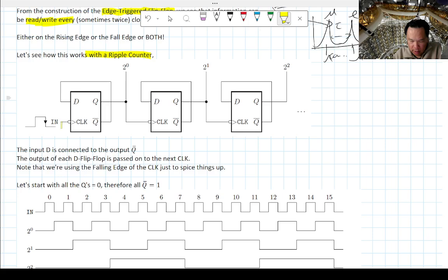The construction is that you have a D-type flip-flop that takes an input of a clock, and it can also take data in. Remember, this data actually goes into two gates, one for R and one for S, but the S is inverted compared to the R. It has two outputs, Q and Q bar, and they're always going to be opposite of each other. The weird thing is that the Q bar output gets mapped to the input. So there's no external input except for the clock.